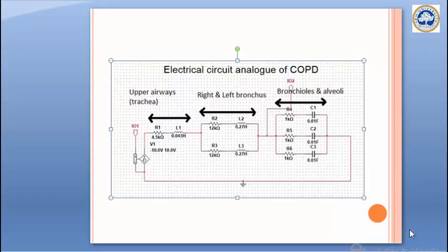For COPD, the parameters altered are R2, R3, L2, L3, R4, R5, R6, C1, C2, C3 to represent the clinical condition. The input to the circuit is a voltage controlled power supply producing square pulses with an effective on time of 1 millisecond to maintain the inspiration expiration ratio as 1:2. The connections on the left and the right ends are the hierarchical port connectors that can be used to control the input to the circuit once the circuit has been imported into LabVIEW.